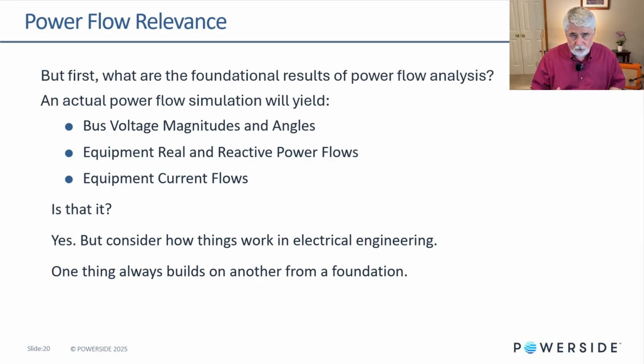In an actual power flow simulation tool, the actual results that will be yielded from the simulation are bus voltage magnitudes and angles, and equipment real and reactive power flows, and current flows. So is that it? Yes, literally that is it. When you solve the solution, that's what you get. But remember, consider how things work in life and in electrical engineering. One thing always builds on another. So our foundation are these quantities.